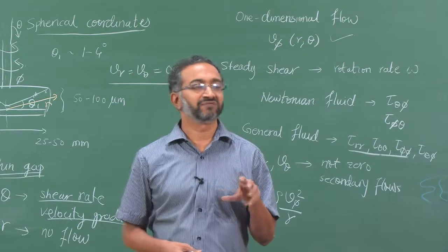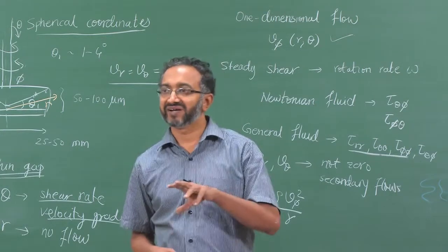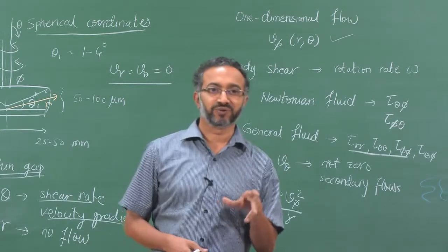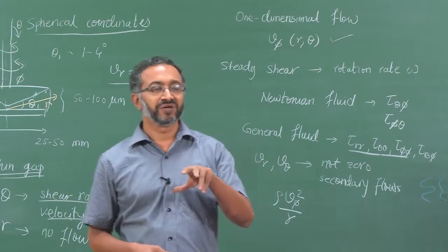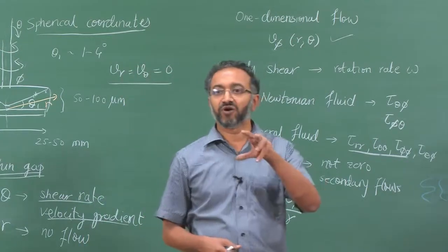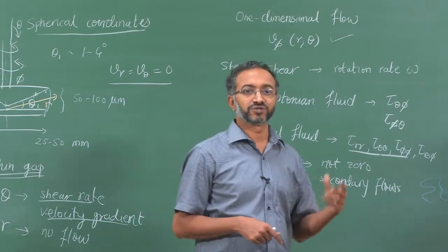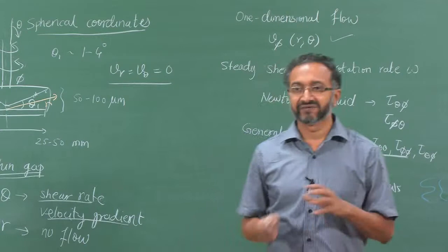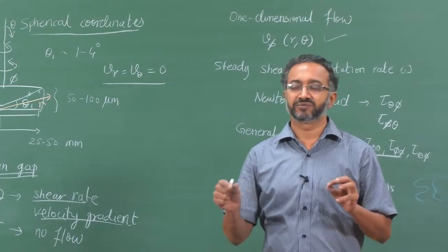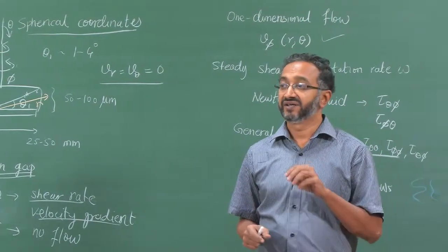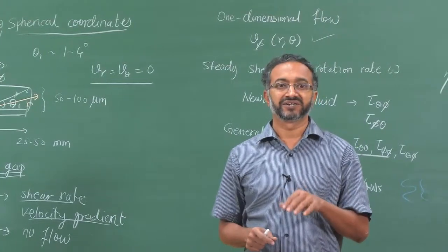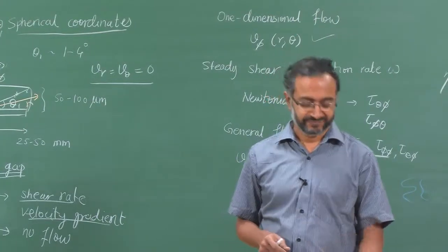So, instead of applying 1 micronewton it might apply 1.5 and then it will adjust and come to 0.5 and so on. So, it will not be able to apply a constant stress, but it will wobble around that because of its control capabilities and the instrument operations. So, whenever we are looking at limits of the instrument operation, we should be careful that instrument response may be being measured as opposed to the material response.